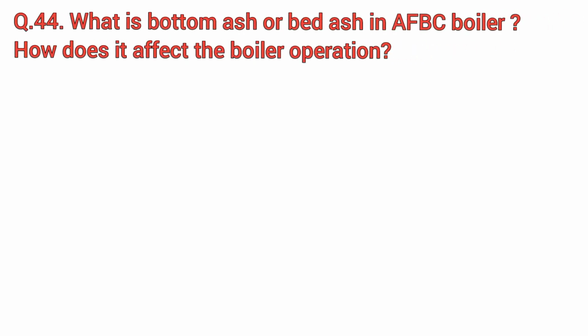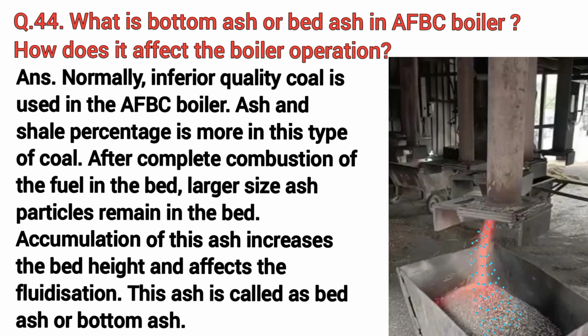What is bottom ash or bed ash in AFBC boiler? How does it affect the boiler operation? Normally, inferior quality coal is used in the AFBC boiler. Ash and shale percentage is more in this type of coal.